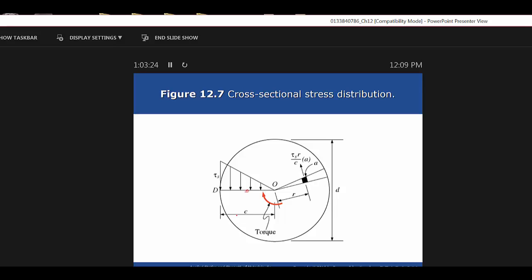Actually, you take each one of them and raise them to the fourth power. It's kind of like what I did on that homework, on the brass, where the piece had a solid steel core. You tried to subtract the diameters and then do the area, and you can't do that. The same thing here. Don't do that here either.